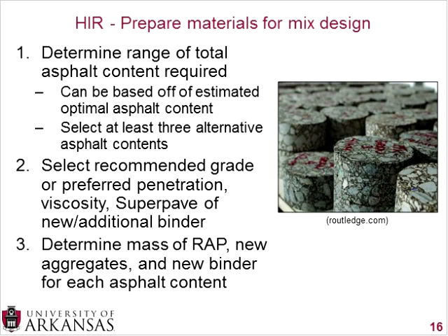But now there may be some additional things that we're looking at. How do we obtain representative samples from the field? How do we break down those samples in the lab so they're representative of what's in the field? And then also we may be adding a rejuvenation agent or rejuvenating agent, because one of the big things that we're trying to do is kind of rejuvenate this layer because of the heavy oxidation on the very surface. So that may require some special care.